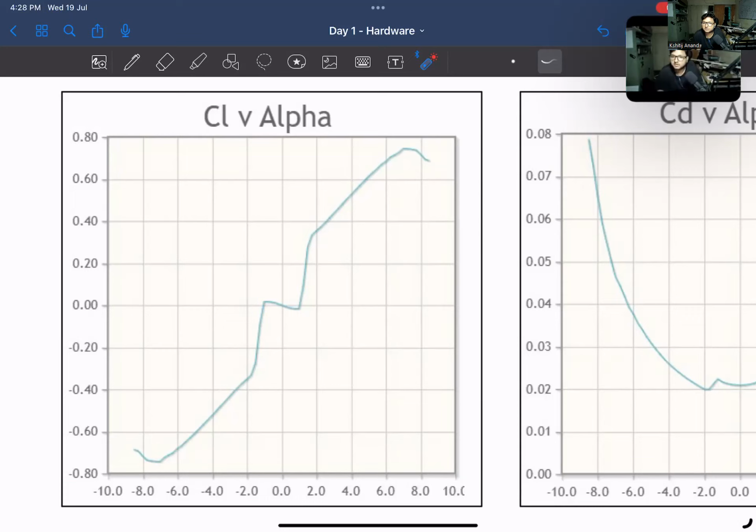It's more or less transient, it's not a permanent effect. The small negative lift that you are seeing at lower angles of attack, you'll have to go into the nitty gritties of the pressure distribution, but more or less it settles to a zero or positive lift coefficient after a while.